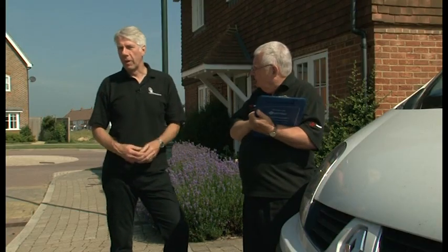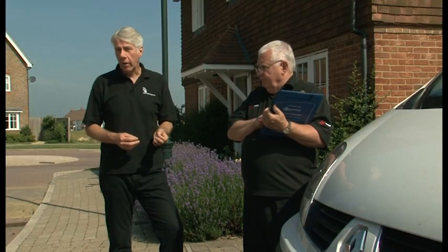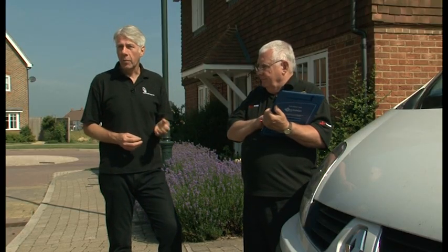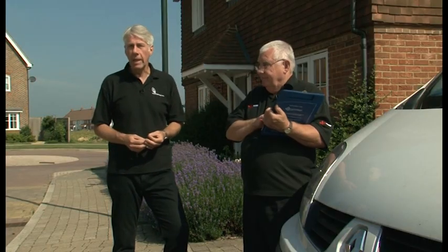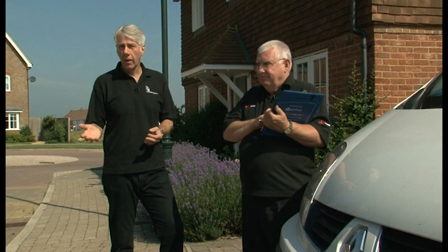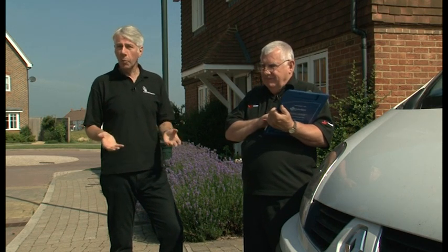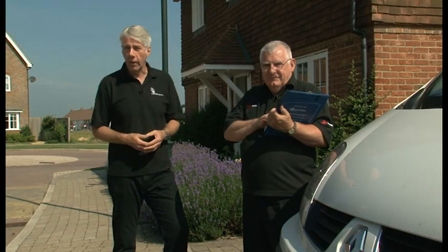If we didn't have previous results, then sampling must not be done, because if we do say only 20% of the circuits, we'd have absolutely no idea of the condition of the remaining 80%, which, thinking about the MOT of your car again, would you be happy if only 20% of it was checked? Therefore, parts of it could be dangerous, as could your electrical installation.